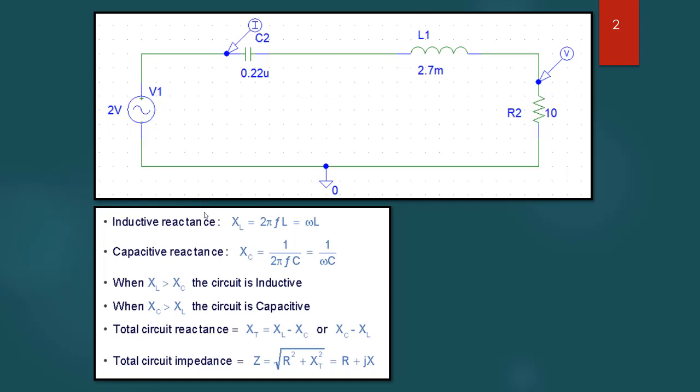Now, the reactance of an inductance can be expressed by XL equal to omega L. We know omega is equal to 2 pi f, so we can express XL as 2 pi f into L. Now, if we plot this as a function of frequency, in the x axis we are varying our frequency, and in the y axis we are plotting the value of XL.